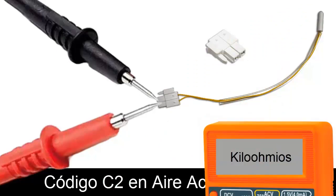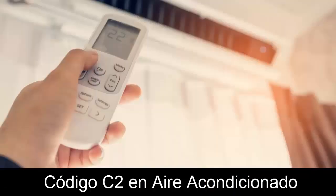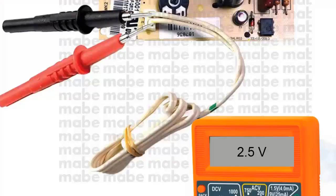E. If everything seems fine, try turning on the unit. Connect the sensor and check if the electronic board is supplying voltage to the sensor. Use the multimeter's DC voltage scale. Expect a reading of around 2.5 volts.